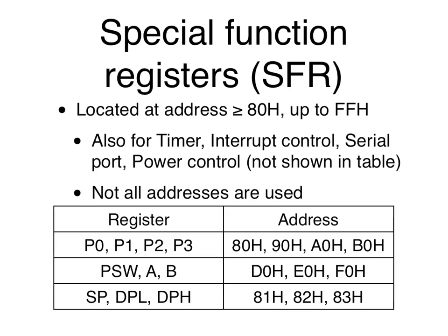And now the original 8051 doesn't really do power control. What's power control? That's like going to sleep mode. And sometimes there may be different sleep modes. Okay, and how do you do that? Well, again, you move some bytes or some bit pattern into one of these special function registers, and then that causes not data storage, but actually some effect, right? So you could put the processor to sleep, you can set a time to wake it up, or something like that. Okay, so everything that has to do with all these so-called side effects are done through special function registers.